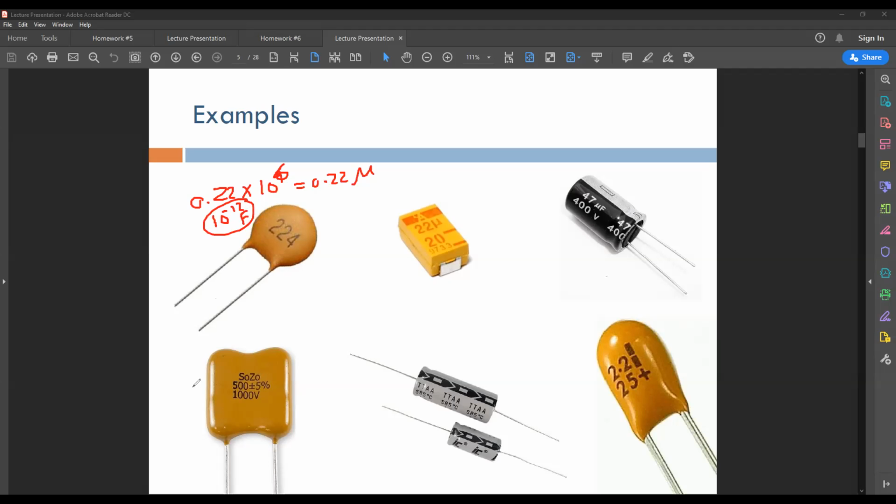How about this? You have 500 what? Picofarad, right. It's not very difficult, by the way. Everything is picofarad, unless it's otherwise specified, like this, for example. 22 micro. This is written right there. Whenever it's written like this, see here? Written very clearly, okay? When it's written like this, then there's no doubt about it. This is just the regular value. Whatever is written is the one that you use.